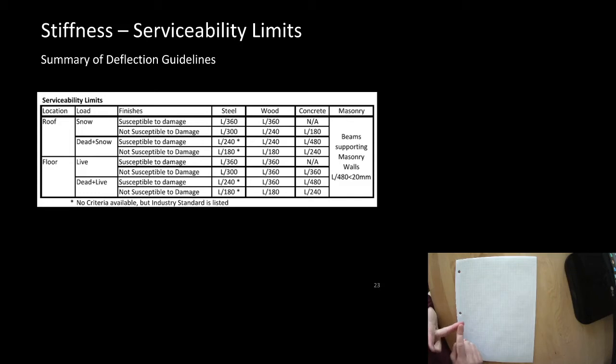We want to know how much shear force, axial force, and moment are in it, so that next term or next year, we can calculate how much it actually moves and make sure it's less than how much it's allowed to move. Calculate the actual axial load and make sure it's less, or calculate the axial resistance or capacity of the element and make sure it's greater than the load. We want to be able to calculate the capacity of the shear value and make sure it's greater than the factored shear. We want to calculate the capacity for moment and then make sure it's greater than the factored moment.